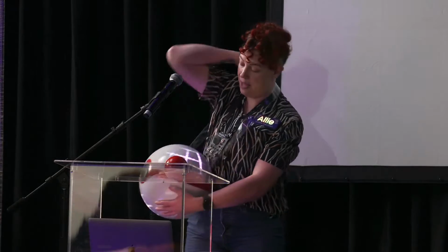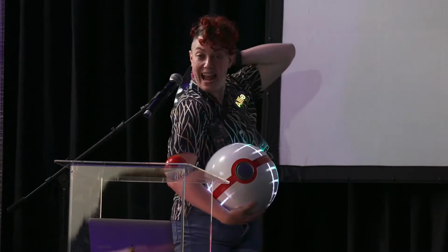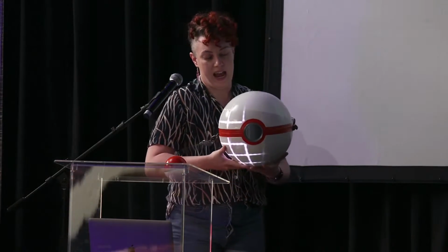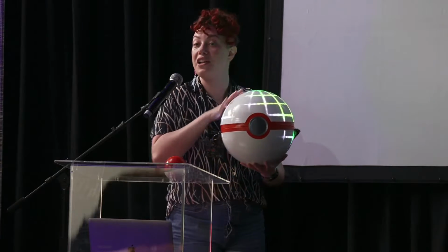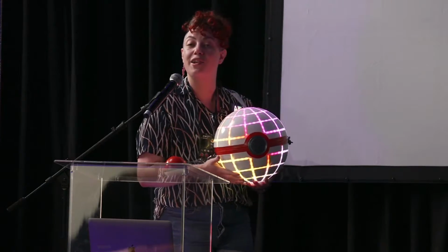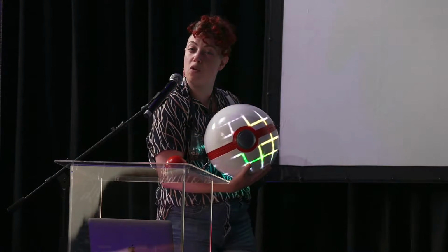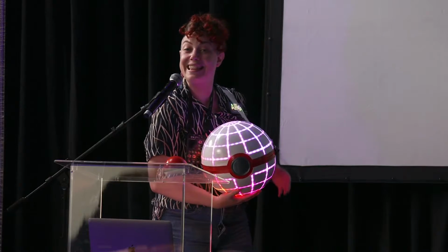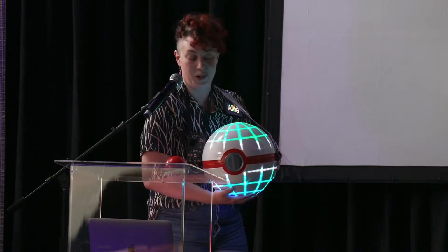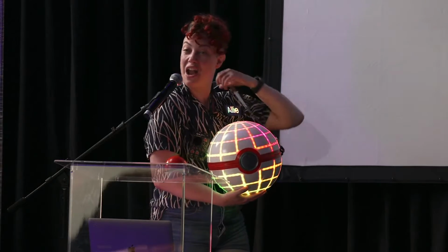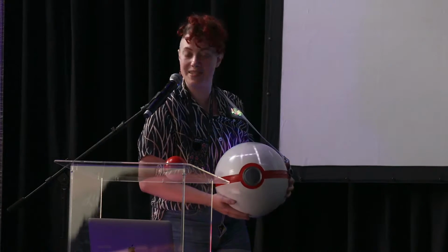For the big one, because I knew the Polisher wouldn't work for that, I actually applied it by hand. I basically got nitrile gloves, a spray bottle of IPA, and I would spritz down and hand smooth it one area at a time. I would then let it sit for a little while until it was not tacky anymore, and I would do it again. And I did this until I reached a surface finish I was okay with. Not the fastest for these large things, but it's totally doable. You don't have to do it with a vapor smoother. You can just do this by hand.